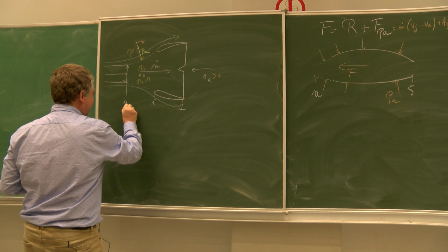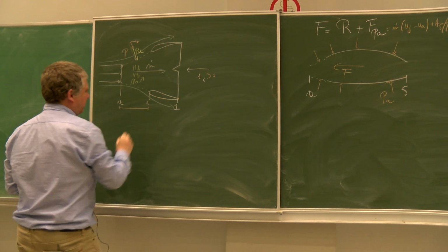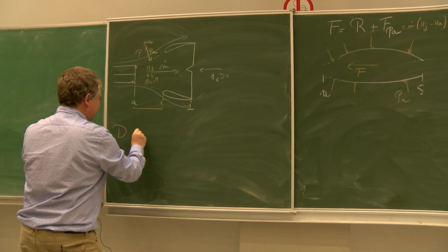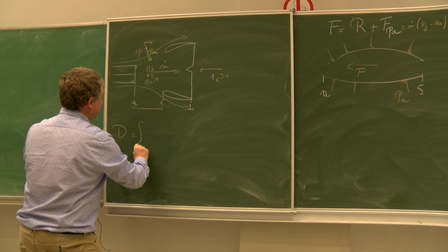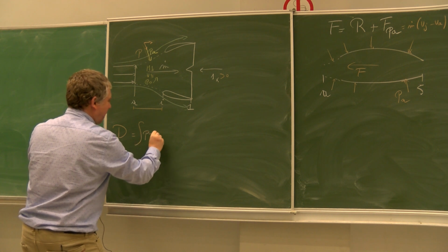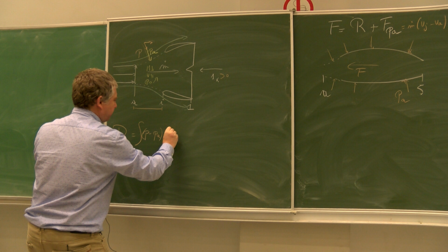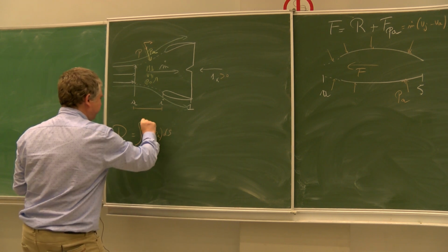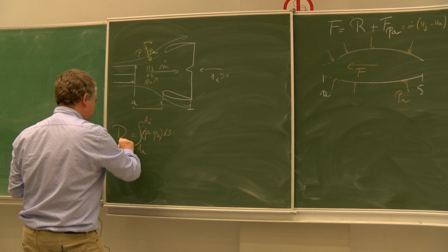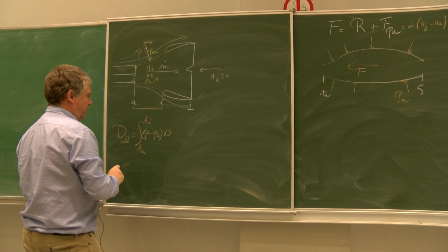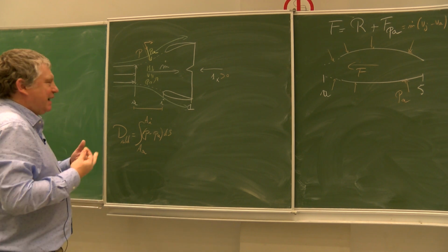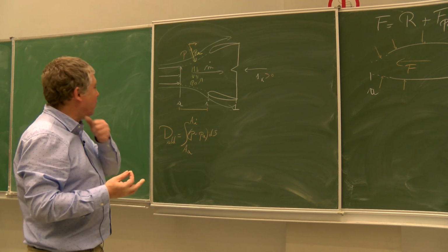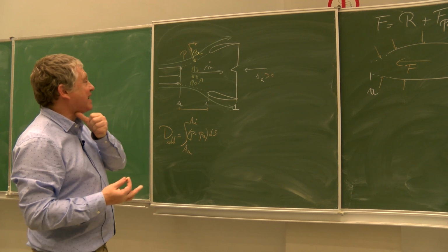And so this section between A and I is delivering a drag that we can compute by integrating P minus PA multiplied by the surface on which it is acting, between the section A and the section I. And this is what we call the additive drag. The additive drag is a positive drag, which is a negative thrust.